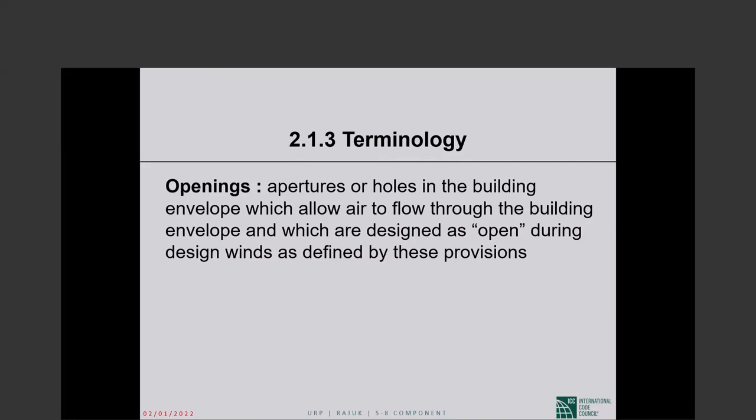Opening, this is an extremely important definition. I cannot overemphasize this. Apertures or holes in the building envelope which allow air to flow through the building envelope, and which are, this is the important part, designed as open during design winds as defined by these provisions. So an opening,